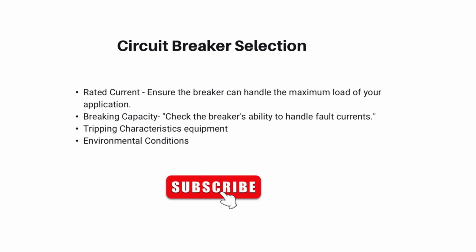Then the other thing that you also need to consider is the breaking capacity. Check the breaker's ability to handle fault currents. Then the other thing that you need to know is the tripping characteristics. Your selection should be based on the specific needs of your equipment, whether you require instantaneous tripping or delayed tripping.